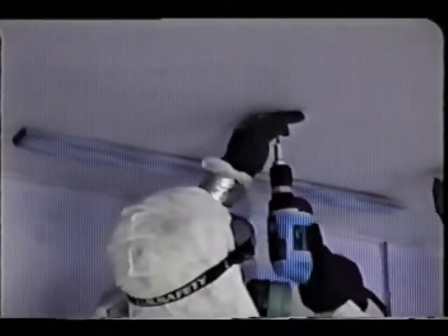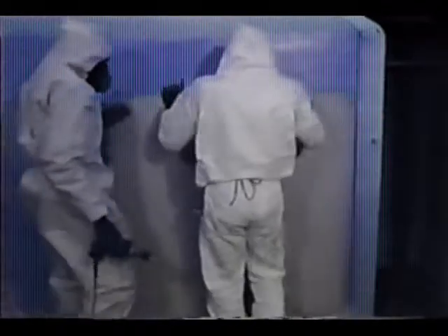Enclosure is the installation of a rigid, durable barrier that is mechanically attached to a building component. Components such as walls, ceilings, trim, and floors that are coated with lead-based paint are potential candidates for enclosure. For example, walls and ceilings that have deteriorated lead paint can be enclosed by attaching 1/2-inch drywall to them.